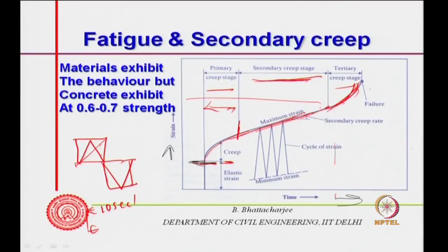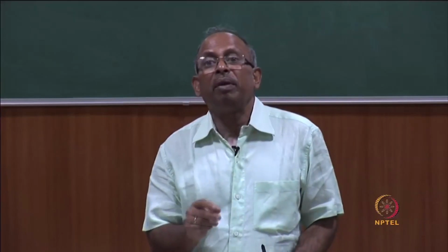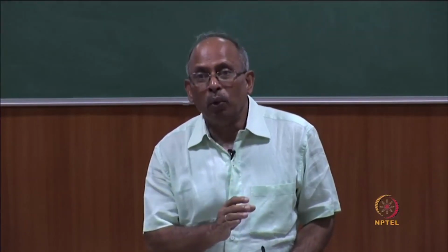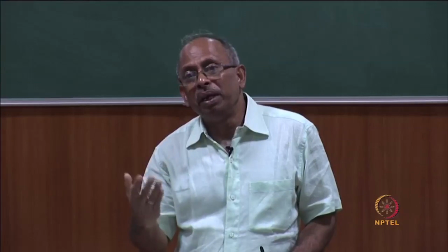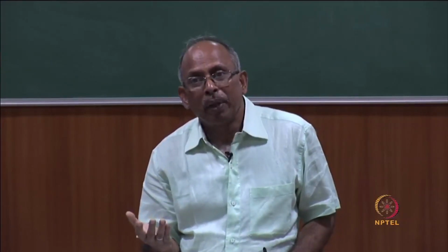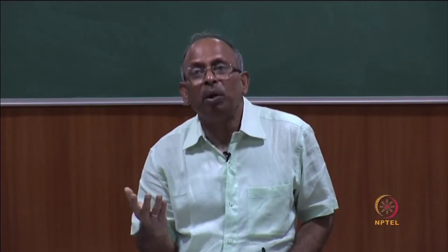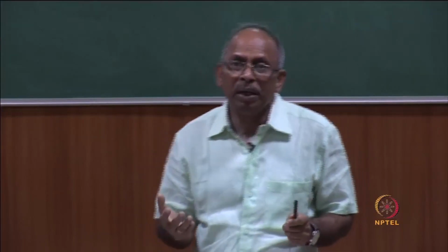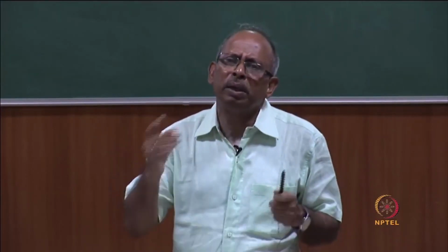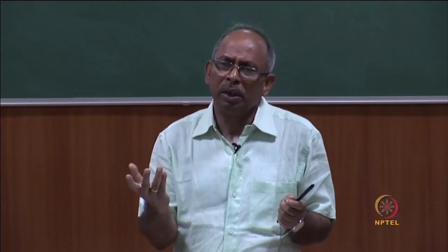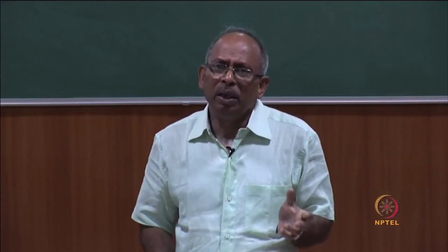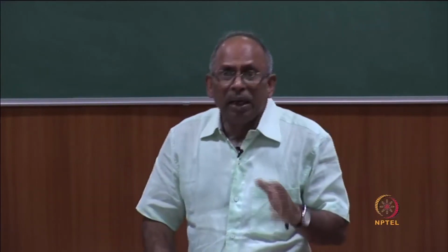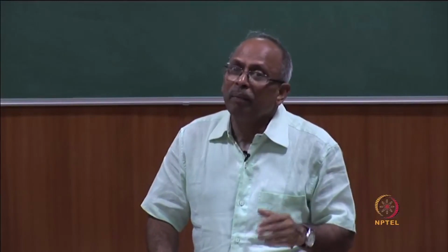So, fatigue is a case where reversal of stresses occurs at a very fast rate, cycle time is low, but if the cycle time is infinity, it is actually sustained loading. If the cycle time is infinity, that is a very long time to complete the cycle, practically my load is constant. So, that is actually sustained loading. So, there is a relationship between sustained loading and fatigue.